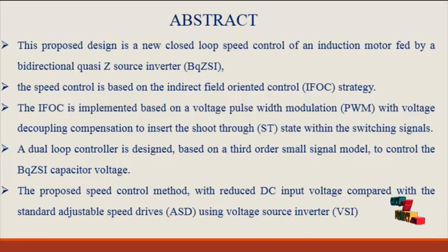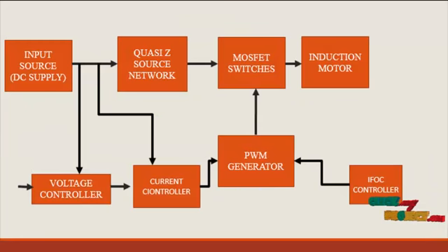Also, the proposed inverter can be operated with simple PWM control and can be designed at higher switching frequency to reduce the volume of passive components. The proposed inverter can realize buck boost inversion and power conditioning in a single stage with improved reliability. In addition, the proposed implementation has the unique advantage of lower component ratings. This is simulated in the MATLAB simulating environment. Next we see about the flow diagram of our product.